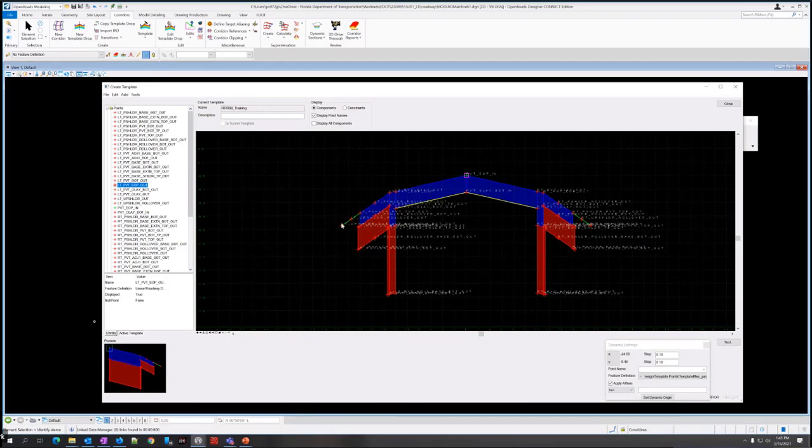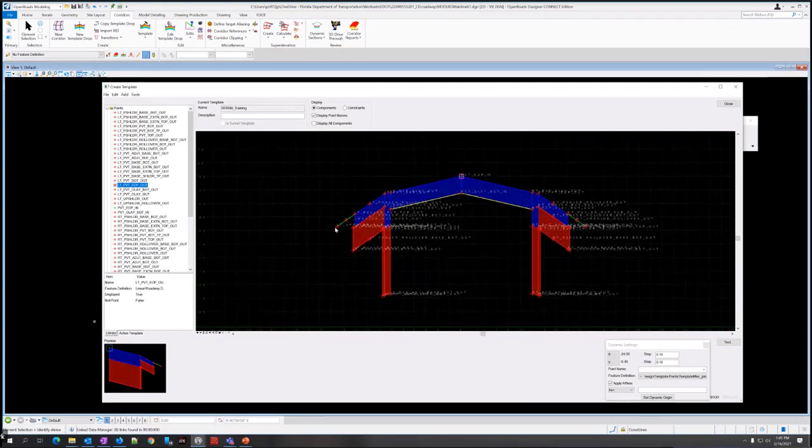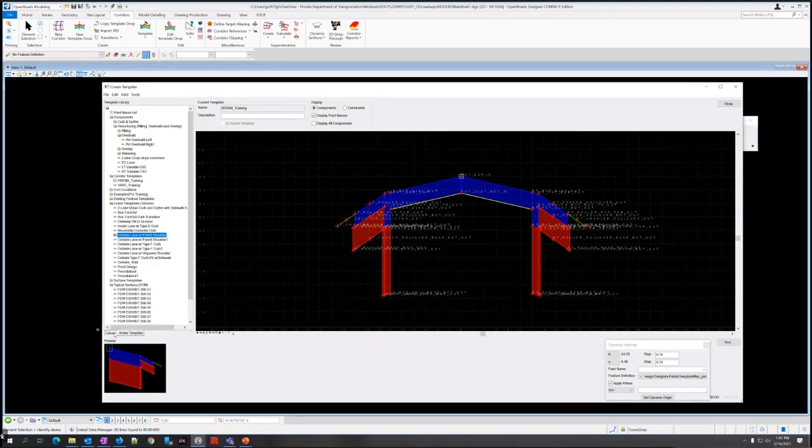Since I hadn't covered this yet, and I dove right in, just so you're familiar with how this is going to work to build a corridor, essentially we're taking this. It's like a typical section really, and it's going to put it in a corridor like a cross section. It's going to use it, repeat it over a set interval to build a 3D model.